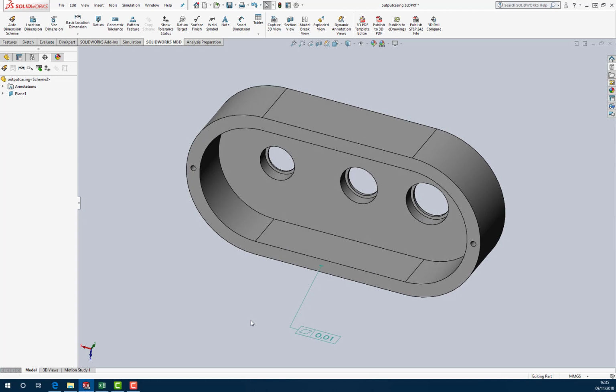So essentially, all of the surface must be constrained between two parallel planes with 10 microns between them. So it's a bit like if you draw a mountain range and you've got a peak to valley height of 10 microns. It's not a very tall mountain, is it?